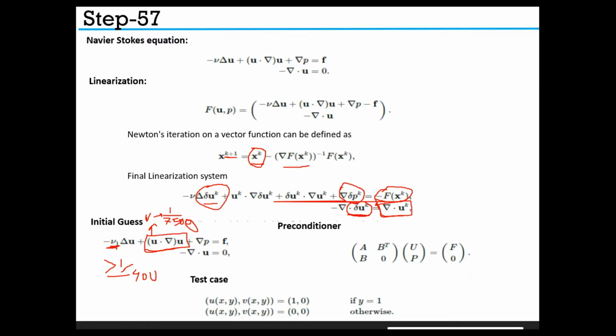So in this situation we use the continuation method to set up a series of auxiliary Navier Stokes problems with viscosity approaching the one of the target Navier Stokes. Though the initial guesses are something different, the final guess would be like that. In this process, the sequence of viscosities Vi is determined experimentally, so that the final solution can be used as a starting guess of Newton iteration.